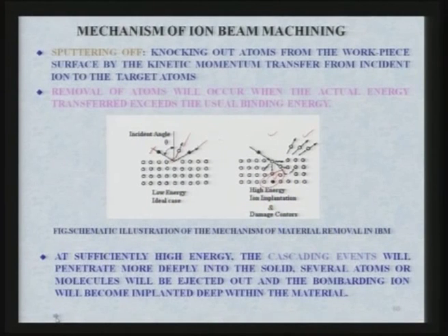So, removal of atoms occurs when the actual energy transferred exceeds the usual binding energy of the atom with reference to the surrounding atoms. At sufficiently high energy, the cascading events will penetrate more deeply into the solid. Several atoms or molecules will be ejected out, and the bombarding ion will become implanted deep within the material, as you can see over here. So, this is not the desirable feature.